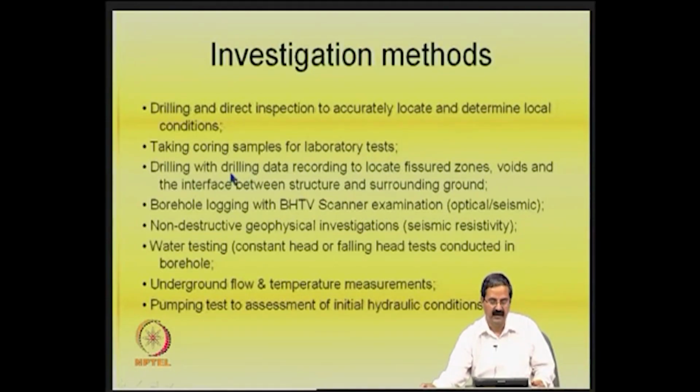Drilling with data recording, when you are drilling, you can locate fractured rock zones, voids and the interface between structure and surrounding ground. Sometimes the interface is a critical issue in many problems. So, you must be able to get all that information, and we also have what is called borehole logging with borehole TVs and cameras.